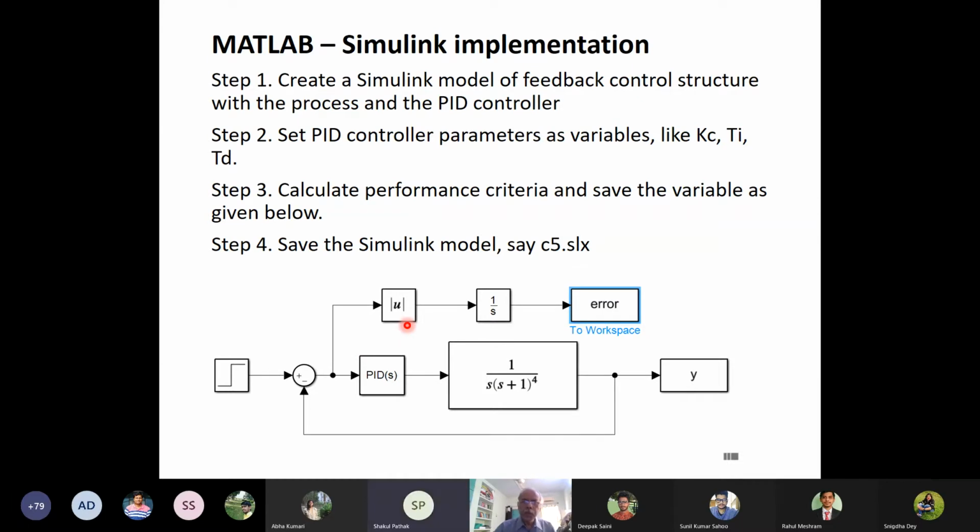Okay, so if you have to do it for both together, then in that case, you have to give step response for both the disturbances as well as the set point. If you do that, then you can do it for both together. So there is no limitation that it has to be done for the servo or for the regulatory problem. You can use both the problems simultaneously or sequentially.